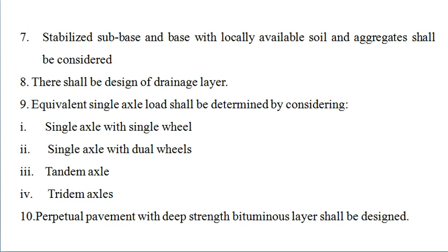was recommended, and there was a need regarding the design of the drainage layer. Now, as we know, the pavement deteriorates when water is introduced into it. That can be from the surface or by side penetration of water into the pavement layers. Now, if there is a provision of a drainage layer in the pavement, it shall drain off the water present in the layer, thus increasing the durable span of the pavement.